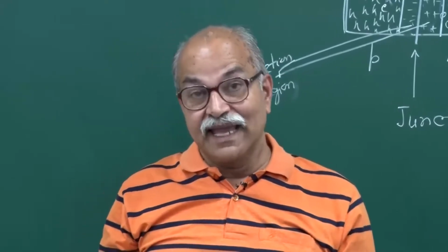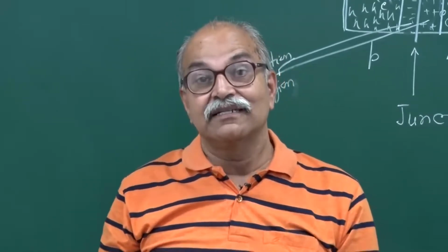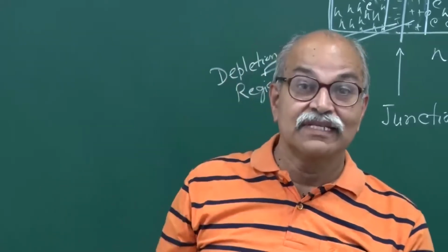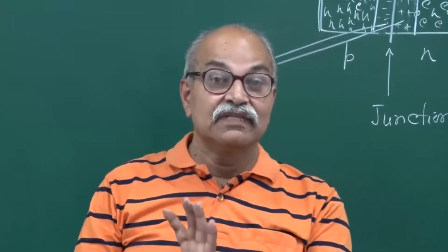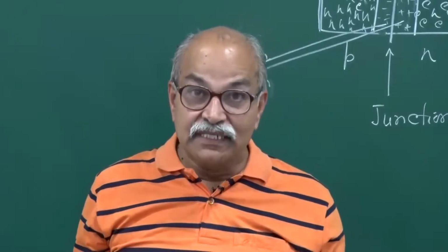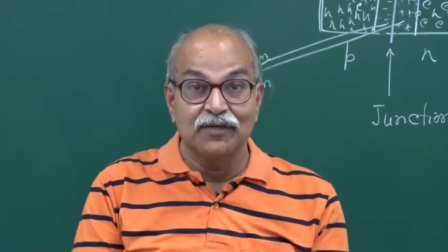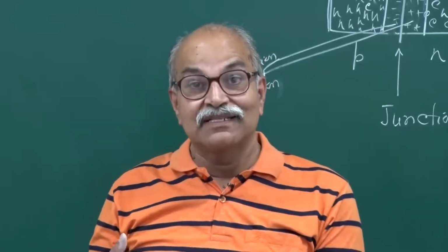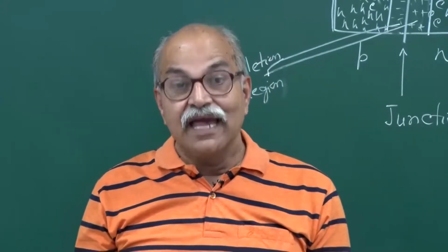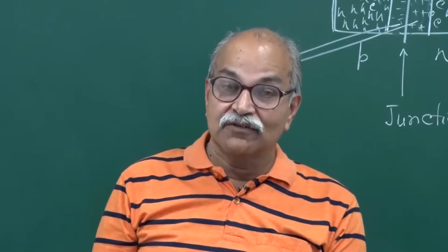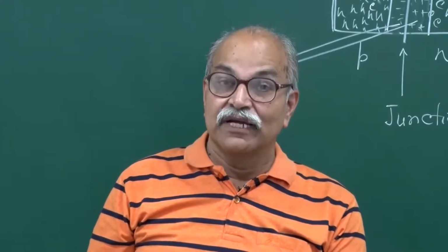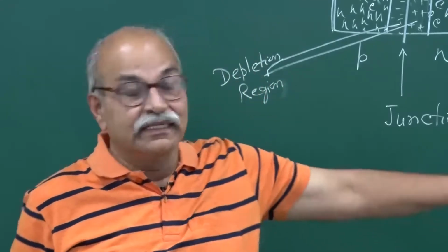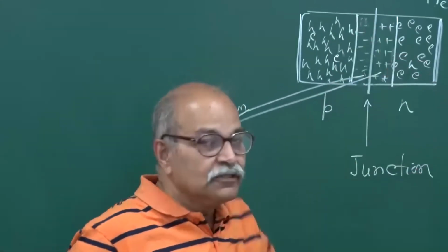These electrons can get energy from the crystal of the order of Boltzmann constant k times T. Because of that thermal distribution, energies are taken up, energies are given away. So new electron-hole pairs are always created, and the old electron-hole pairs are destroyed in a normal semiconductor. That process is still here in this depletion region also.